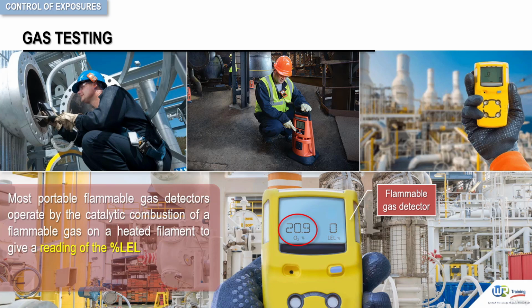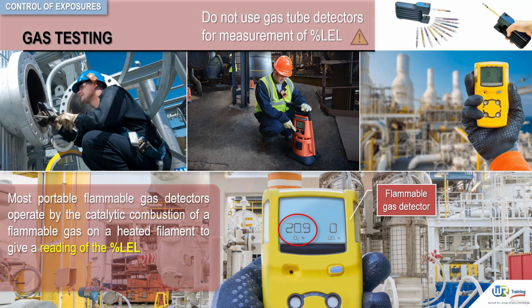If the atmosphere being tested is deficient in oxygen, for example, after being purged with nitrogen, it is not possible to use a standard type of flammable gas detector to detect hydrocarbon vapors. Flammable gas detectors must be maintained, calibrated, and operated in accordance with the manufacturer's recommendations in order to give accurate results. Always use the correct instrument for measurement of oxygen, LEL, and percentage of toxics. Do not use gas tube detectors, which change color upon detection, for measurement of percentage LEL. Gas tube detectors are used to determine the presence of low concentrations of a known contaminant, as each tube is designed for a specific contaminant.